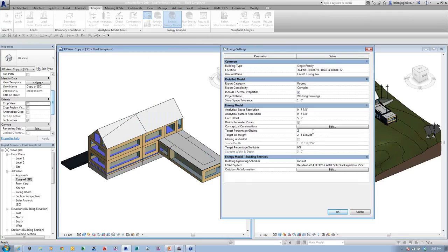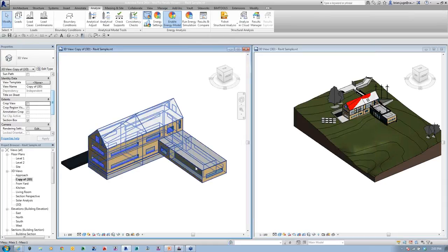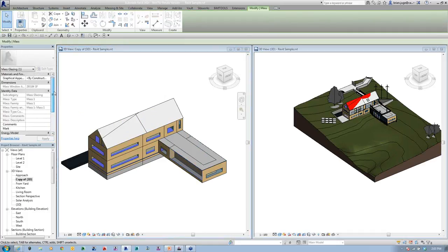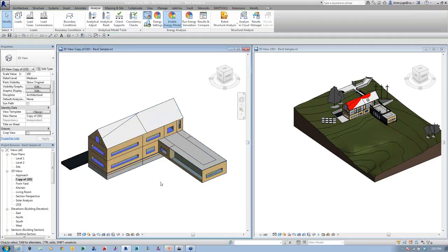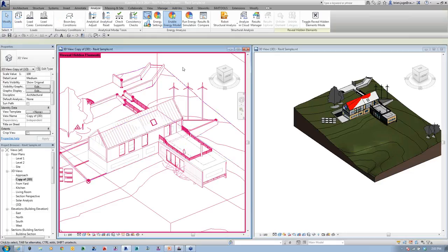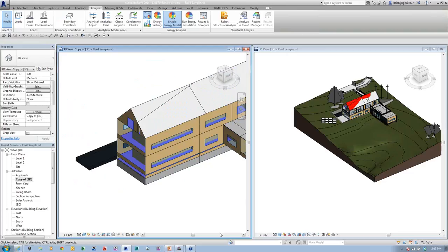Likewise, we can come in here and say, well, maybe there's only 20% over the whole building. That model will update, but what I've gone in and done is hit my tab key, whoops, tab, get this area in here. I can actually say, for this particular glazing, I grab this wall instead. This one, instead of using the values from the energy model, I'm going to say is almost full glazing, 80%. So I'm going to come inside and say by surface, and then identify that instead of 20%, 80% of this is going to be glazed. And you can see how it's changing that model out. Oops, I hit my little light bulb there. But that's how we can get it to perform better on the model.